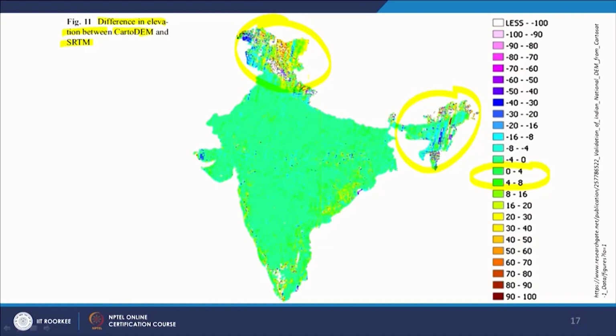So in hilly regions you might have a problem. The same in northeast India or in the western Himalayan region, including Uttarakhand, where the error part is much more. The same in the Kutch region, where you also have some undulated terrain, and also the Eastern Ghats and Western Ghats, and some in central India and the Narmada zone area. Those areas had large errors compared to flat areas in that particular model, Cartosat DEM, validated or checked using those GCPs.